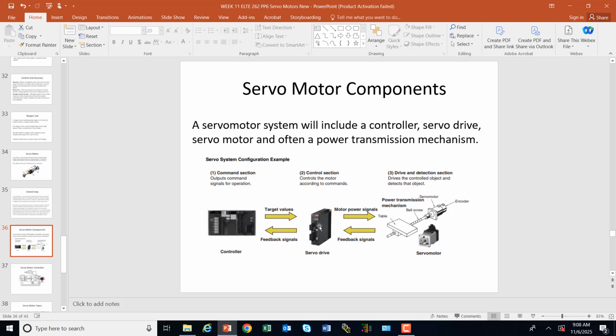It is then going to move that information into the servo motor, and the servo motor will spin. This is going to control the spinning of the motor. The motor's got encoders on it, so it's going to be talking back and forth to the servo drive to be sure that it is doing what the PLC told it to do.